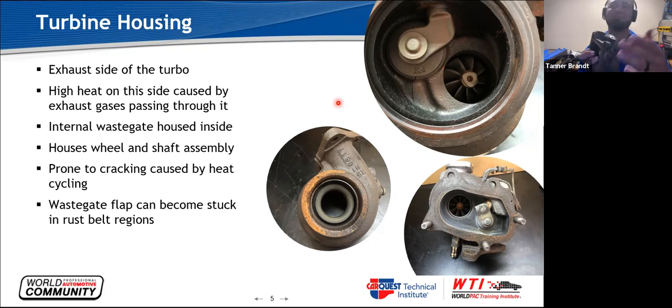Once that happens, you can take it apart, you can free them up, but on most stuff it's so hard to get to the turbo that if you're going to take the turbo all apart to do that, in my opinion, you're probably better off just selling them a turbo. But it is doable. You can heat them up and free them up. It's not a huge deal, not super hard to do. Again, if you take that off, just make sure that you don't adjust the actuator that's attached to it.